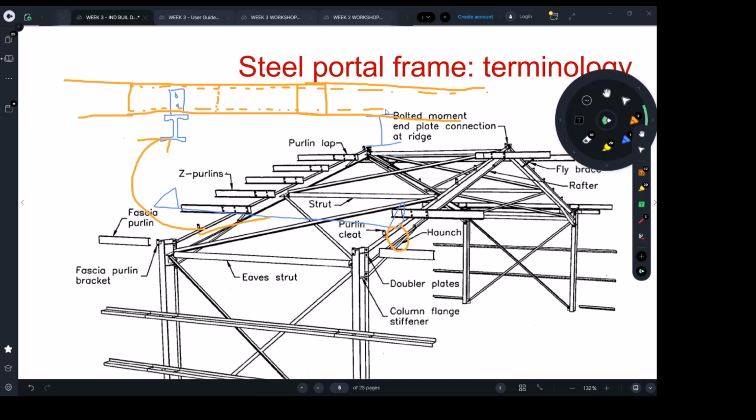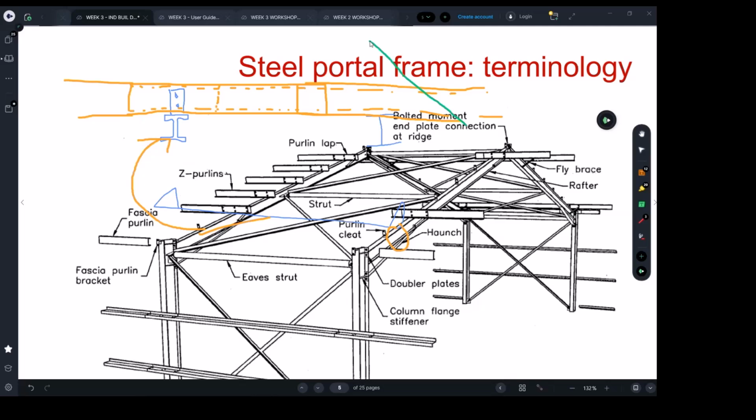But nobody knows what I'm talking about in terms of bending. Bending moment diagram, usually it goes negative at the support and goes positive between the supports, like this. This is positive and this is negative. So lapping above the support means how many purlins do we have effectively? This is a simpler question.